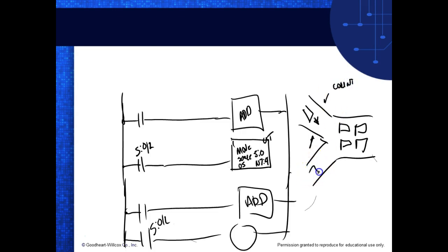And over here, when these come through, this is going to be another counter. You understand? Then my instruction, I would come up here and say add the accumulator for counter. So if this is counter 1, my add instruction would be add, and my source A would be counter 1. My source B would be counter 2, right? You understand? And then we're going to put it somewhere.